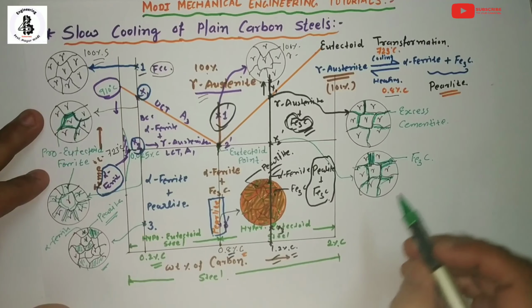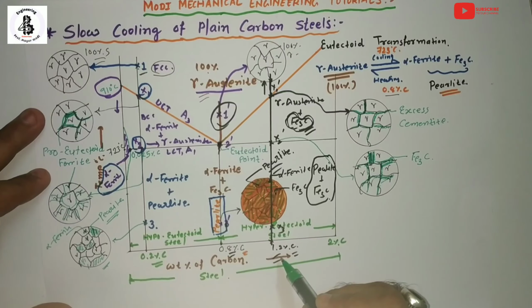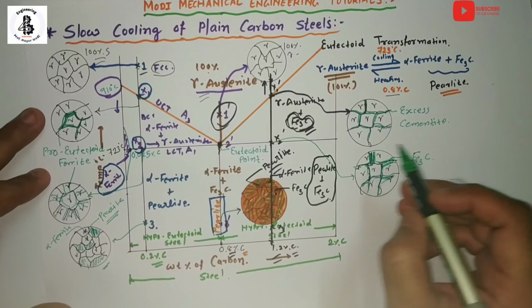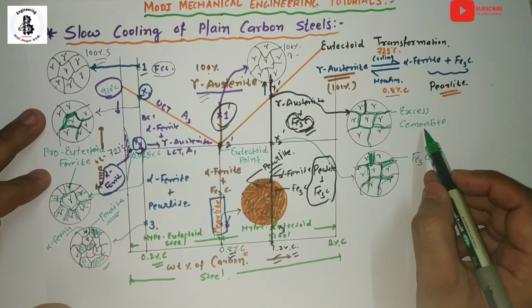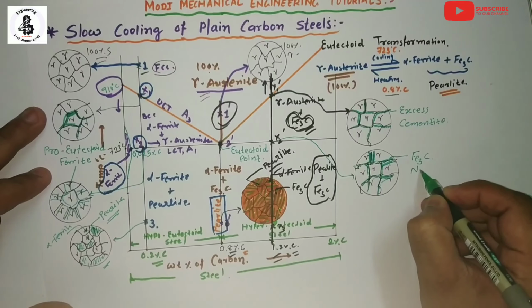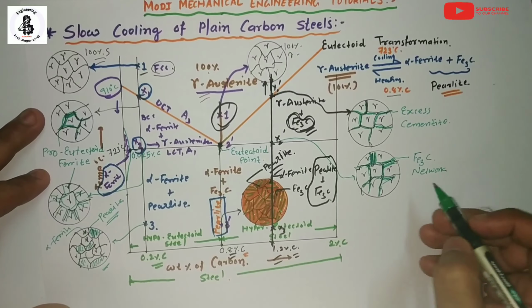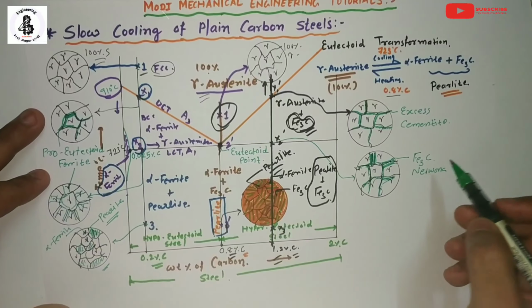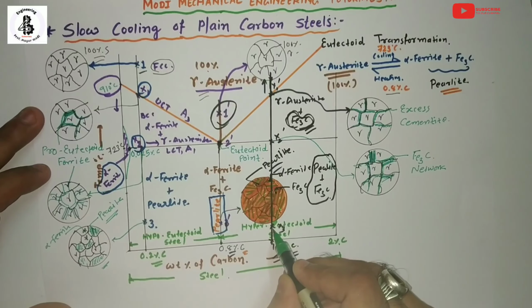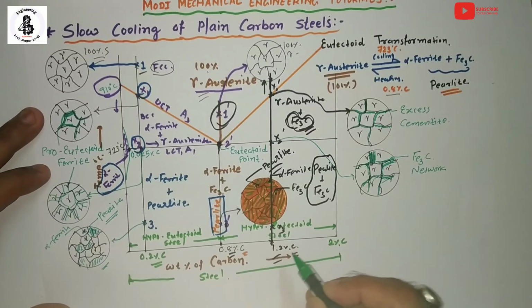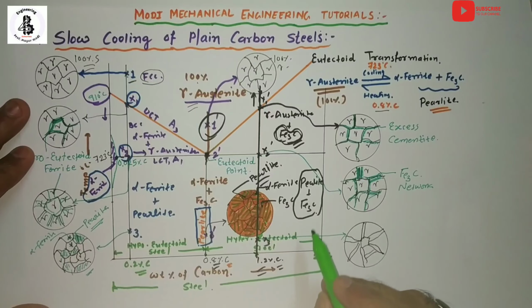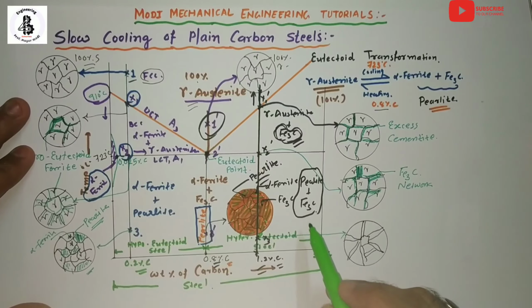So by slow cooling with the higher weight percentage of carbon, around 1.2%, there will be expansion of the cementite network. So initially the cementite is present, but at the lower temperature the Fe3C will form some networks. So now it will be totally converting into Fe3C and pearlite. So now I would like to make a microstructure at the x3 point. So here at room temperature for 1.2% of carbon, at room temperature, there will be the formation of the pearlitic structure plus cementite structure.